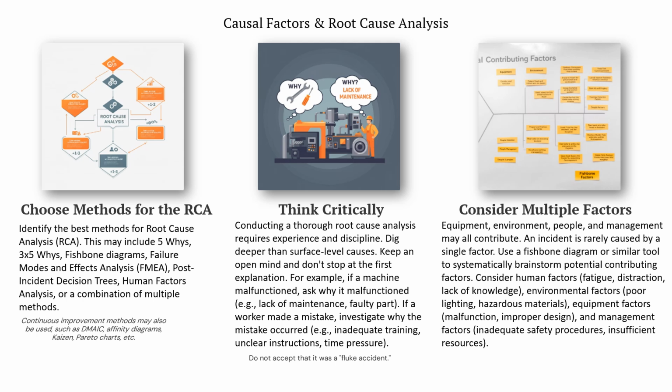Next, consider multiple factors. It could be equipment, environment, people, management. They may all contribute to the incident. An incident is rarely caused by just a single factor. You can use a fishbone diagram or similar tool to systematically brainstorm potential contributing factors.